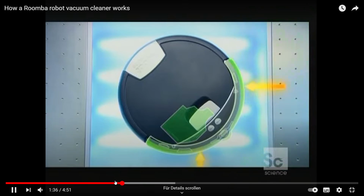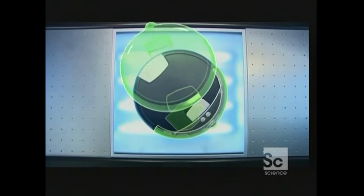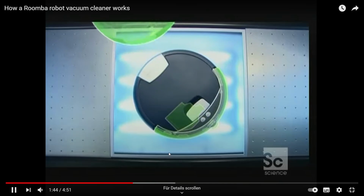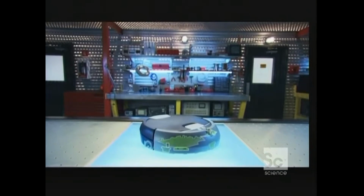If the sensors are triggered one after the other, the robot knows it is stuck in a corner. It has two bumpers, so it knows it is hitting left, right, or something in the front. If it hits the front, then both sensors will be triggered. If the robot's infrared light hits the side, it will only trigger the one sensor.